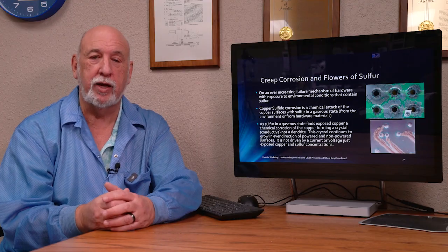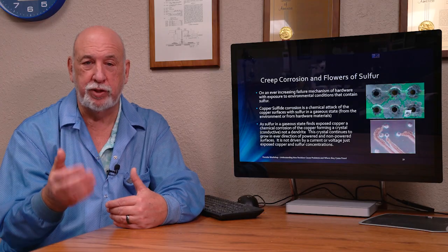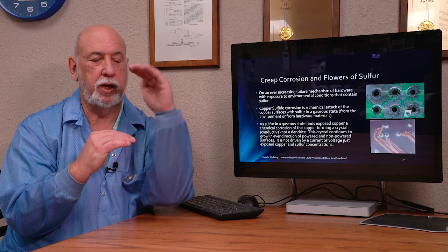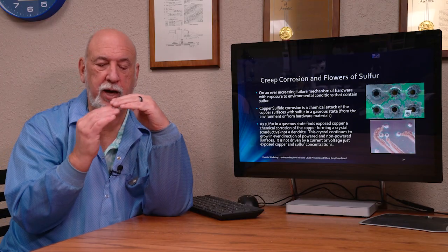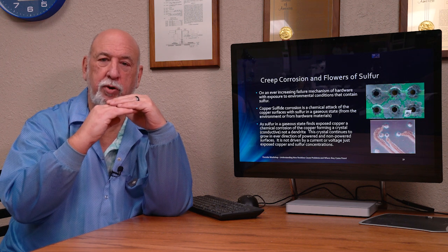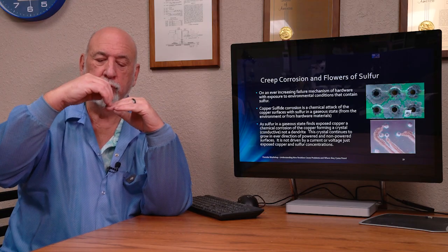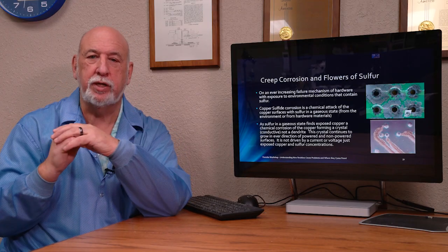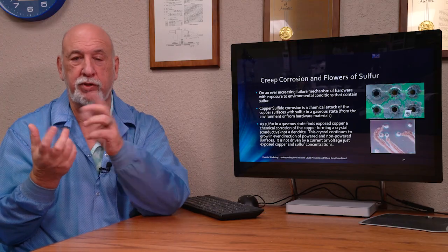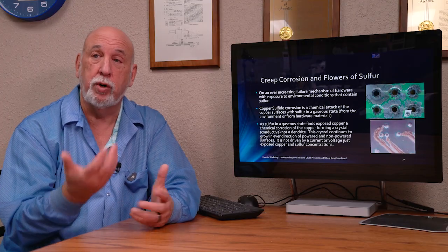It doesn't require power. We also see sulfur reacting with silver on resistors. It will actually pass through. There's a layer of epoxy, and there's a silver layer underneath at the interface, and this is the primary connection to the resistive film material. Well, sulfur will pass through the thinnest part of that epoxy and corrode open, and we'll see copper or silver sulfide corrosion, and it'll change the value of the resistor or take it to the point where it's open.